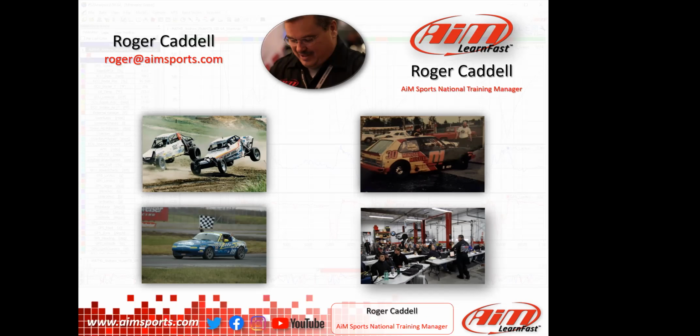And when we started to use some data on some of the off-road trucks and buggies, we were changing not just the rebound and compression damping, but also where it hits, and we're opening these little bypass valves, and it might be 3, 4, 5 stages where these shocks just keep getting at different rates as it goes through the entire process, which makes this data even more important, so we can capture that. Things are moving so fast when those things happen. With data and suspension, things are happening at a high rate of speed, so it makes it very helpful.